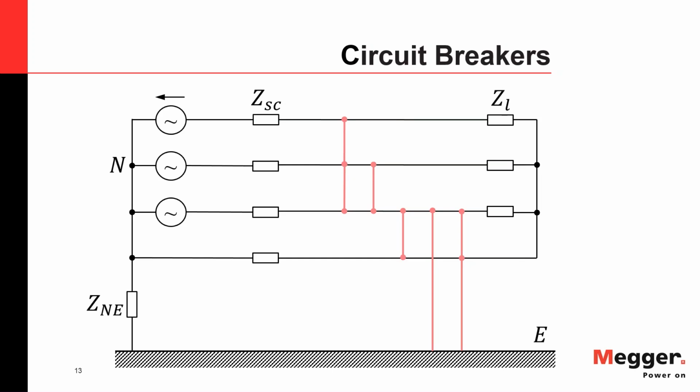All the other faults are pretty much single-phase faults, where one of the phases is touching either the earth or the neutral or both. There's also the scenario where you could have a phase-to-phase fault that then goes to ground. The difference between these faults is just the grounding scheme of your network, which determines what faults can develop and what is not so likely to happen.